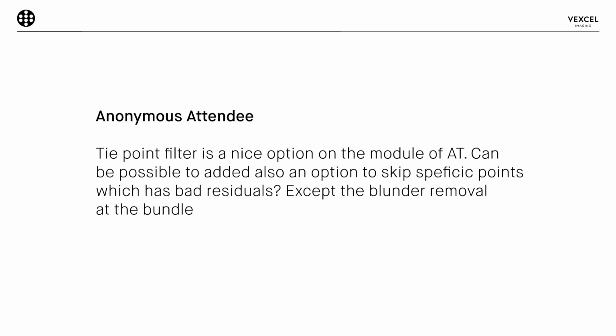Yeah, so the tie point filter is a tool which was developed with the goal of reducing the amount of tie points in a project in a smart way. There are certain criteria to reduce the number of tie points. One criterion is that in areas where there is a high point density, we can reduce the density without losing any linkage of the photos.